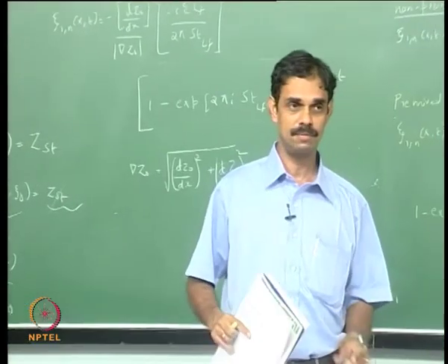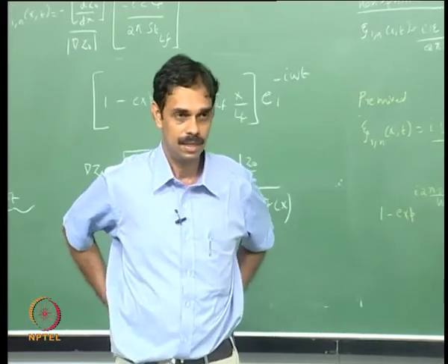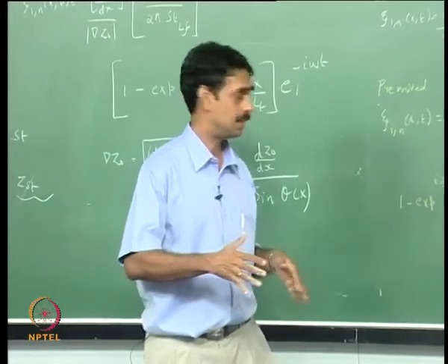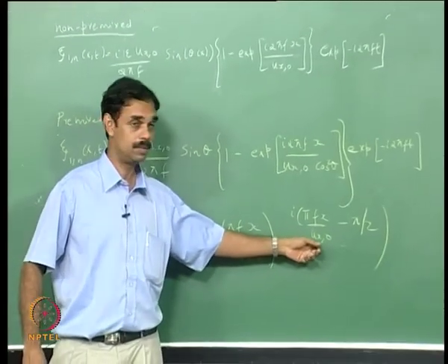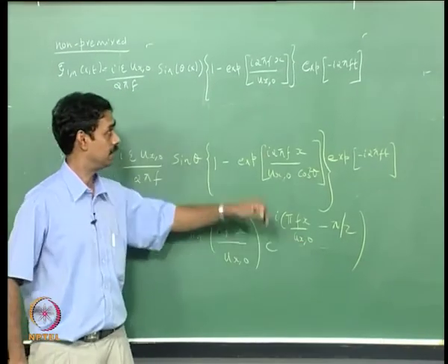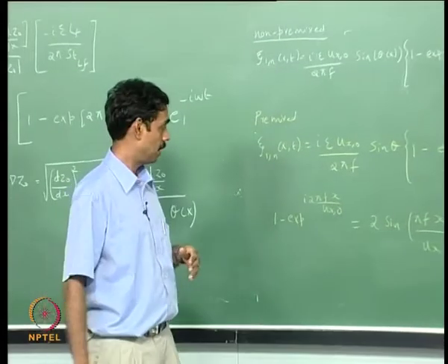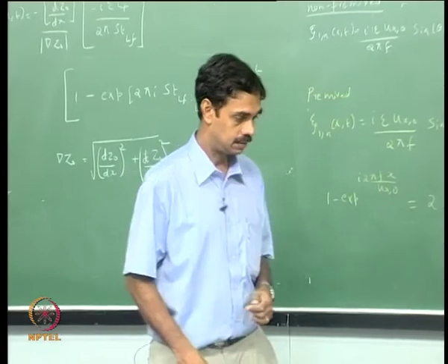So we have studied two different physical phenomena, one with premixed flame and one with diffusion flame, and we are able to see the commonalities, that is both can have wrinkles and both can move, but here the wrinkles move with the convection speed, whereas in premixed flame there is of course a balance between the flame propagation and the flow. I think that is it.